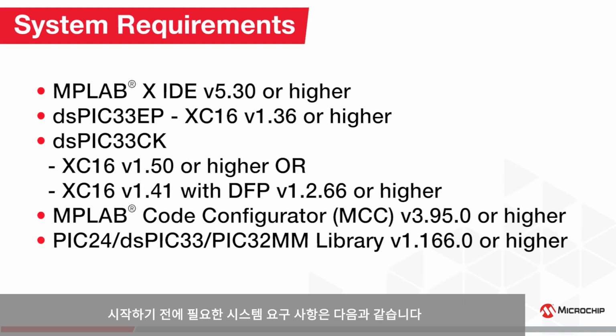Before we begin, here are the system requirements that you should meet. You should be running MPLAB-X IDE version 5.30 or later. If you are using a dsPIC33 EP device, you should use the XC16 compiler with version 1.36 or higher.